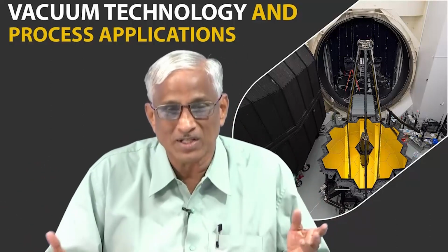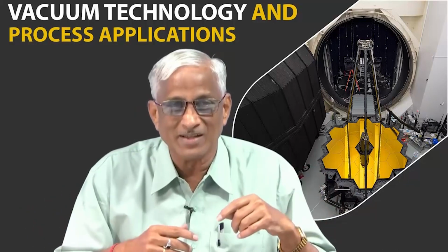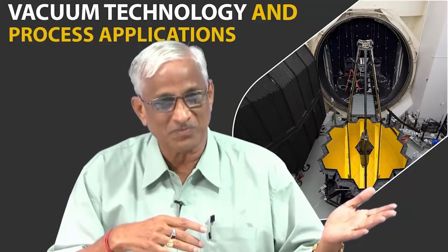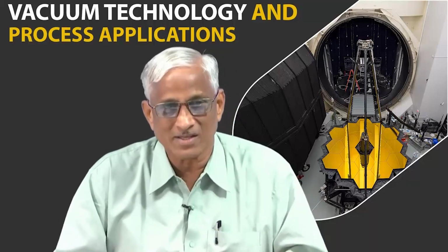In spite of the load, the pumps are working properly, chambers are working, gauges are working, and he also wants satisfaction that without any load it reaches a very good vacuum. Very good vacuum means the ultimate vacuum of a system, which is usually related to unavoidable background throughputs, which are leaks and outgassing. So all parties concerned should always keep in mind to reduce these background throughputs, whether it is a leak or outgassing.